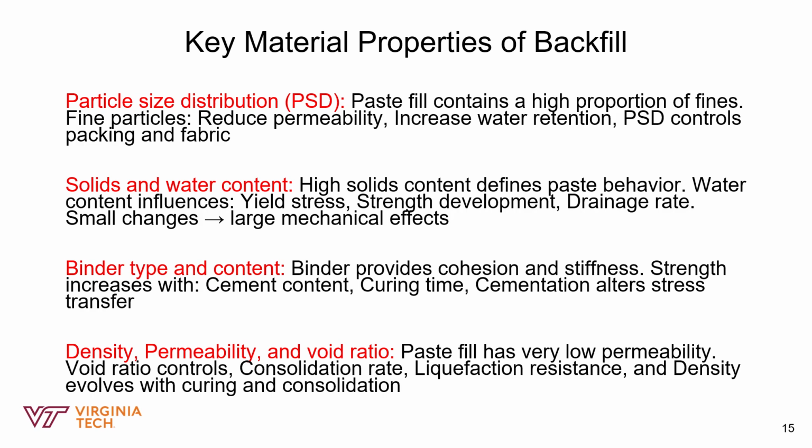The second one is the solids and water content, and this is a very sensitive variable because in paste fill, small changes can create large mechanical effects. Adding just a little too much water can destroy your yield stress and make the material flow too fast, so it's a very delicate balance.